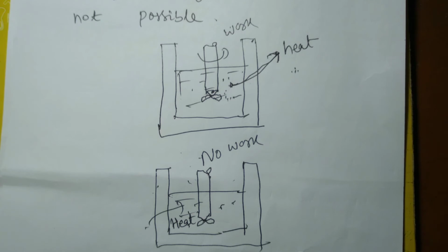So जो second law है, first it tells about the direction of the process. It tells about the direction in which a process can occur spontaneously, or in which direction a process is feasible, or it tells about the feasibility of the process. Secondly, it affixes a quality index to energy and segregates the energy into two types, that is high grade energy and low grade energy. How do you classify the high grade energy and low grade energy? Because low grade energy is not completely and easily convertible to high grade energy. That's why they are called low grade energy.